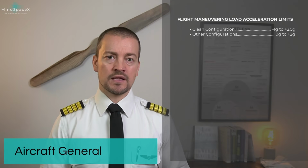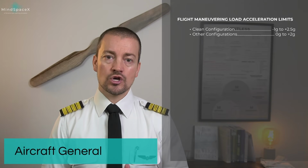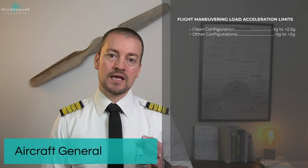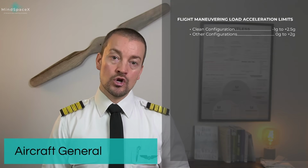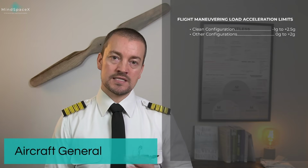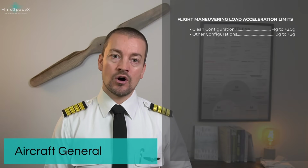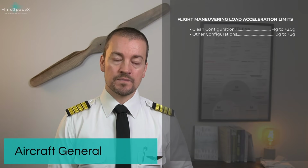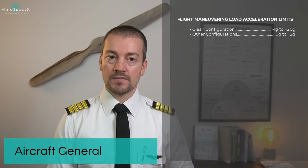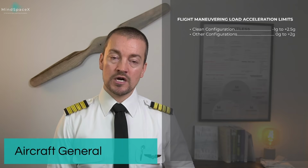We've also, in our ATPL theory, covered the requirements for load limitations on specific categories of aircraft. The transport category aircraft has a maximum load limitation of 2.5 Gs, and this is where our limitation sits as well. Flight maneuvering load limitations and acceleration limits on this aircraft in clean configuration is minus 1 G to positive 2.5 Gs. In all other configurations, the maximum load limitation is 0 G to positive 2 G.